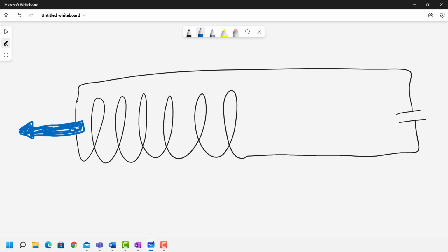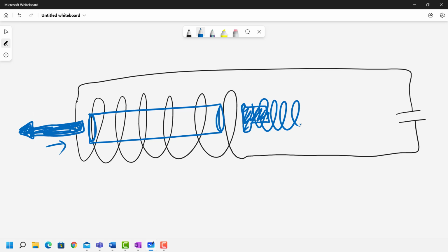What the plastic nib does is it pushes against a ferrite rod. Ferrite rod is inside. But it's a rod, and when you press down the pen, the nib moves, and then it presses against this, which in turn moves. And there's something pushing back on the other side. We'll imagine it like this. There's a piece of plastic. This is just simple plastic. And around it, sort of pushing it, is a spring. Now I know this looks like an inductor, but it's just a spring that's sort of there pushing up against something. So this is there to offer some resistance so that the pen is pushing back against the nib.